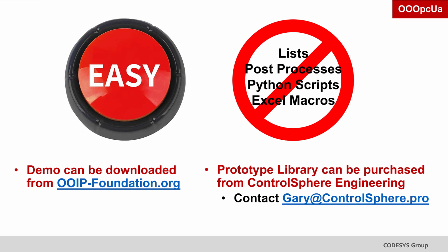Okay, so that is Object-Oriented OPC UA Client. It complements the Object-Oriented OPC UA server that has been available from CODESYS for many years. Just add a little code to make your function block self-contained and self-reliant, and then you're done. Drop these enabled function blocks in your code, configure them, and away you go. And add more to your design later on, and they just start working. No list to go back and remember to modify, no one-off custom Excel or Python macros to build or maintain, just plug and play. The ultimate easy button.